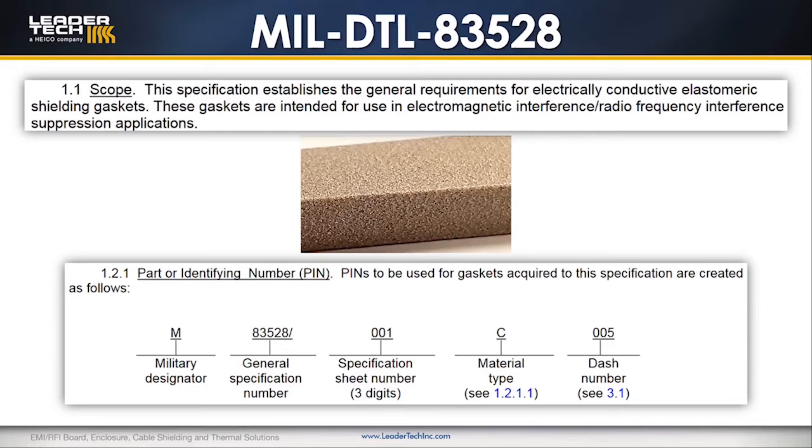These testing and inspection methods have their own requirements and standards as documented in their corroborating MIL or ASTM testing spec. There is a main specification that details the material compounds and their required characteristics, and 16 further specifications that detail their unique part numbering system, which you can see here, and part numbers, standard shapes, tolerances, sizes, all for extrusions, sheets, flange gaskets, O-rings, and waveguide gaskets.